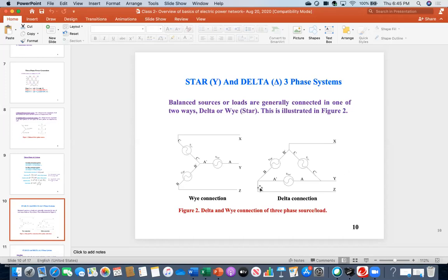Yes, sir. Thank you. And in case of the Y connection, there are some sophisticated methods, for example on the neutral line, and in parallel there is that type of fault current limiter. When it is overloaded, it uses the parallel path to divert some of the current, so that the neutral line does not frequently get disconnected because of overburning or overloading. Do you understand? Yes, sir. Okay, very good.